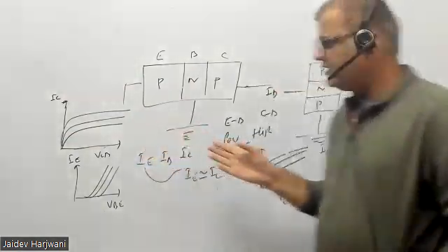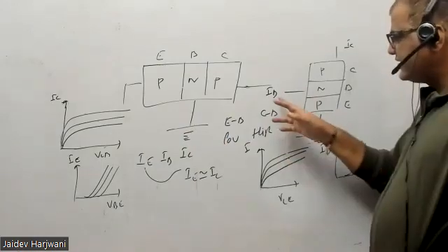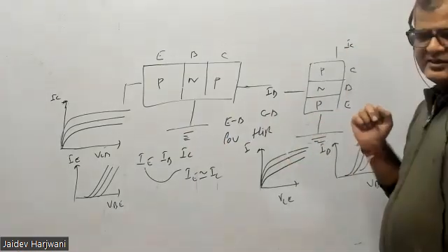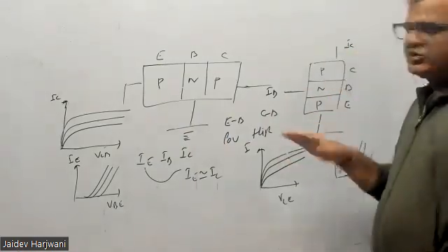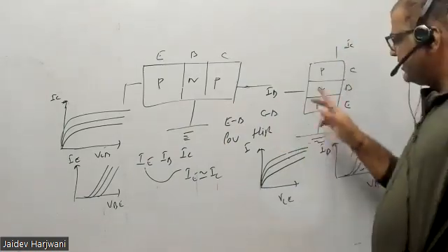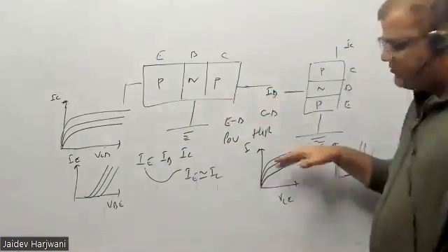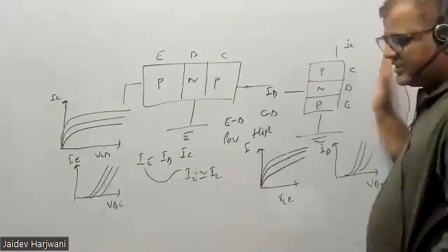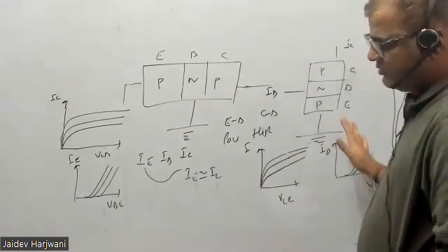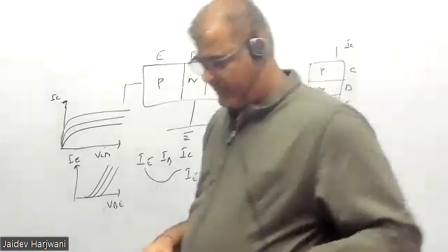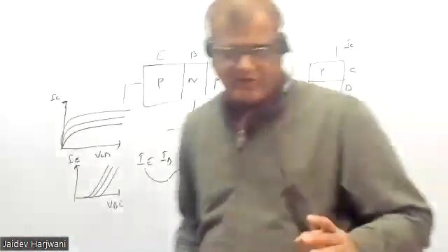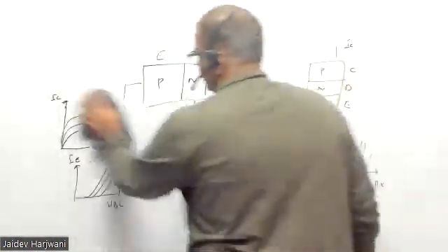Okay, while here you have a current gain as well. Input current is IB, output current is IC, and IC is beta IB. So you have a current gain as well, and the resistance is high, less than the other, but still high. So overall amplification is better with common emitter configuration. So EB junction resistance will be low and BC junction resistance will be high. That you always remember. Okay, what is the option?